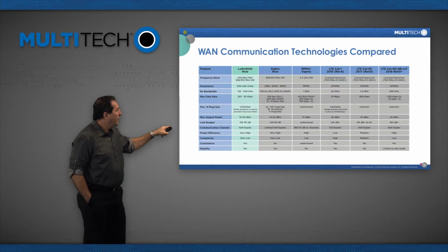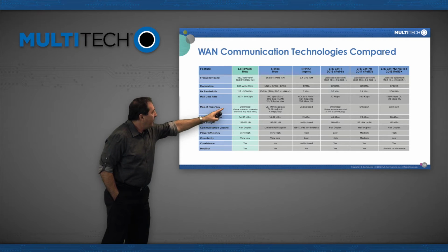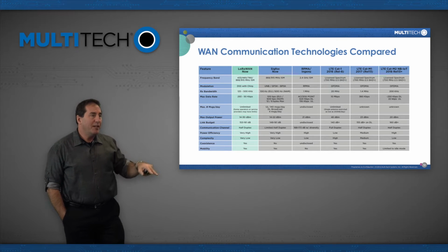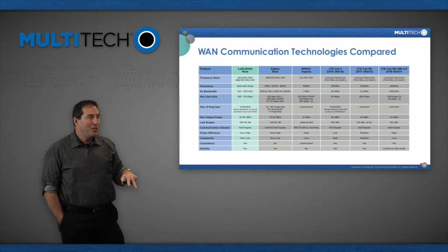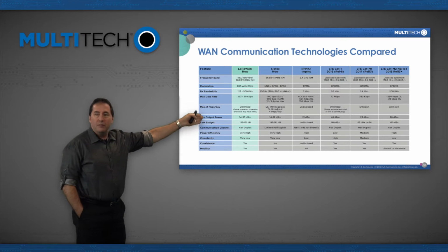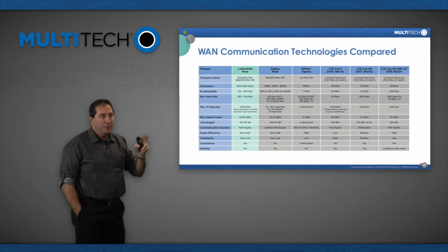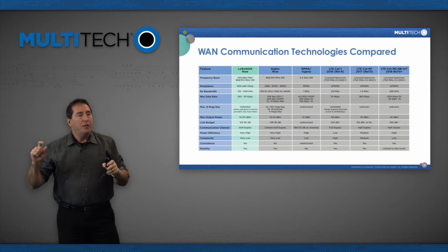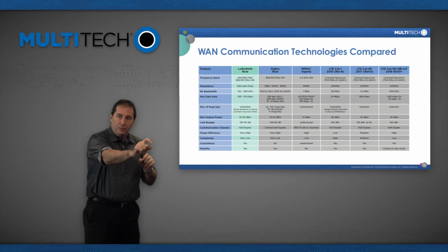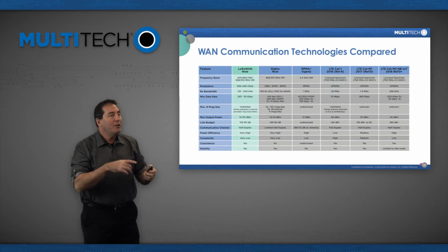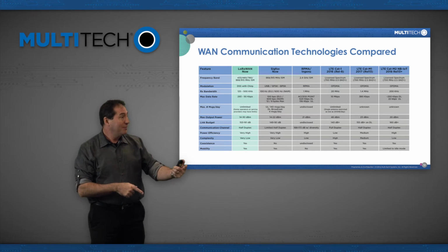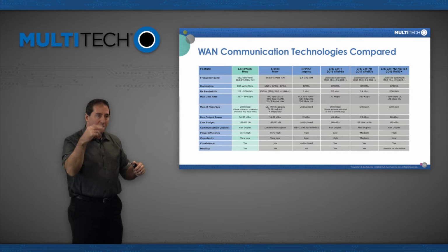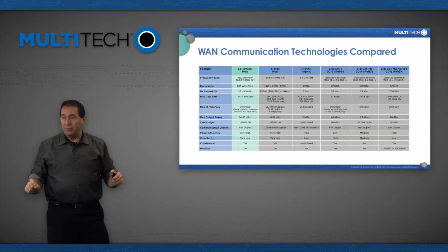But here's some other things too. LoRa is the only one that allows you to do mobility. LTE Cat 1 and Cat M, yes, but they aren't really LPWAN. We included them there to be nice and to give you some additional information, but it's really NB-IoT that is the LPWAN competitor. And NB-IoT, you can't move around. When your device connects to a tower, imagine a dog with a chain to his doghouse, right? You can walk all around that doghouse, and as long as that device is still within talking range of that tower, yes, it can move around.